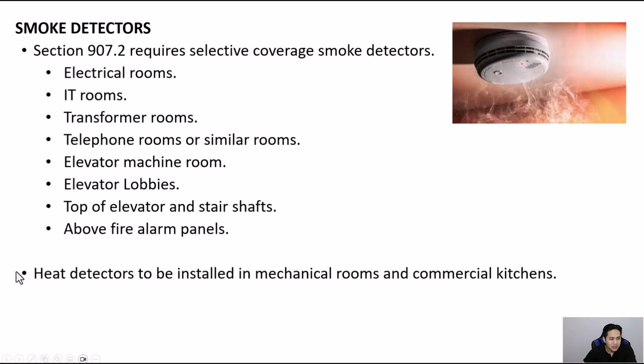And this is required sometimes by the Fire Department of New York. It may also be required according to the local codes of your project. And that's because commercial kitchens can create a false smoke alarm due to the smoke that can be present in kitchens. And also mechanical rooms can sometimes produce smoke, and that's the reason why heat detectors are sometimes required rather than smoke detectors, according to some local reviewing departments, such as the FDNY.